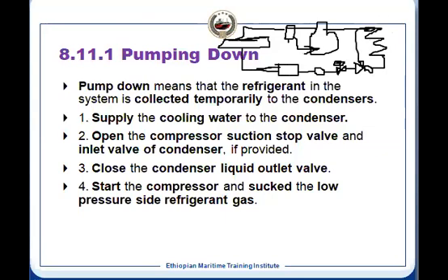This will have a sensor at the outlet of the evaporator. Now, what we do is supply water to the condenser, and open the compressor suction valve. The discharge valve is open, and the refrigerant comes to the condenser. After that, you shut the condenser outlet valve.